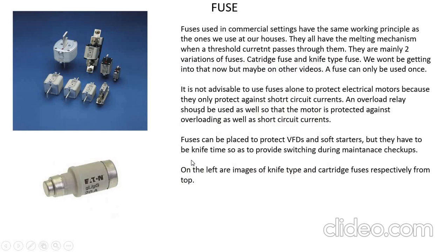And then we have fuses. Fuses are amongst the devices that we use a lot, both for protection against short circuit current and also for switching cases. If we want to do a maintenance checkup, we can use knife type fuses to disconnect from the main supply and so forth.